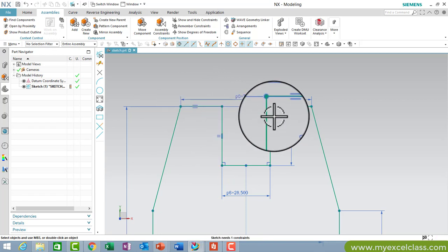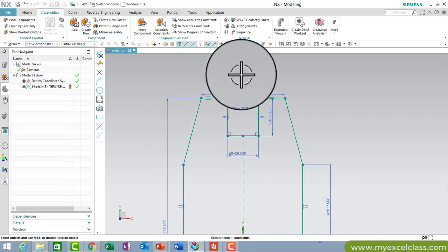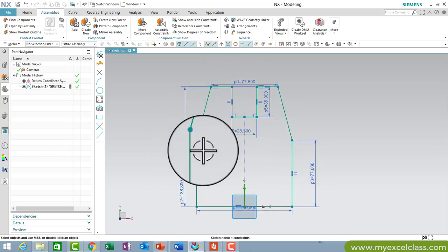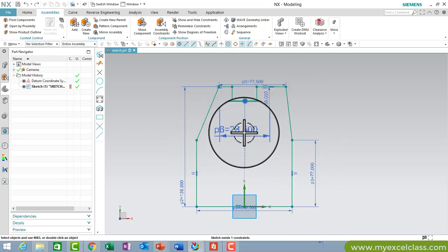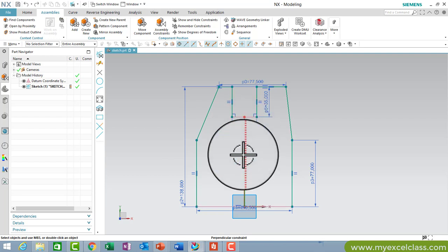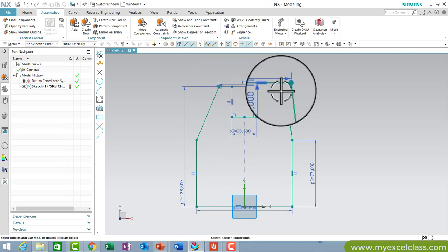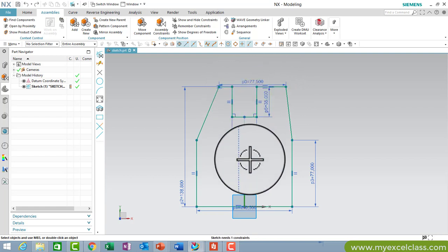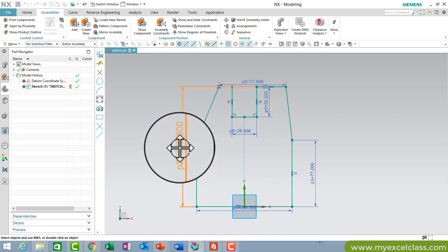So you see, I'll not be able to move this side, okay. So the sketch needs 1 constraint, so let's find out which constraint that is. If you notice, this particular line has a midpoint constraint, but if you remember, we had given a midpoint constraint for the top line, and when we trimmed out that line, that particular midpoint constraint also got deleted, okay. So you need to be really watchful when you're working with the dimensions.